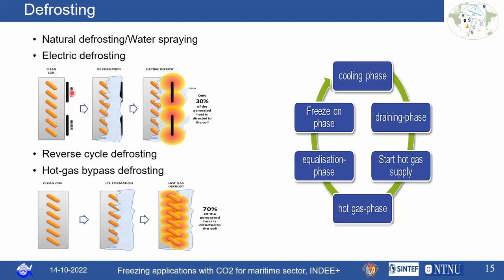So in electric defrosting, you can have electric coils. It is actually a low investment method. The electric coils will heat up the frost that is formed, and it will melt it away. But in this case, your energy consumption will be more.